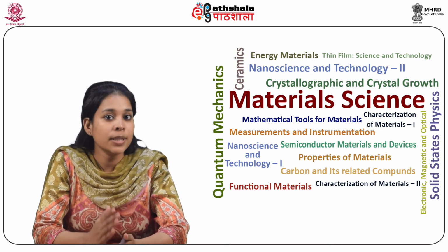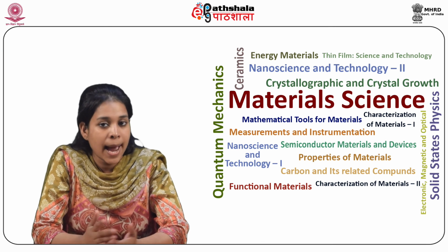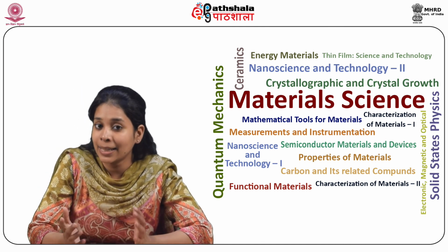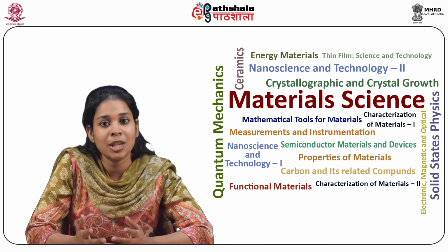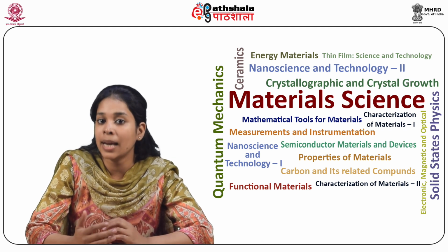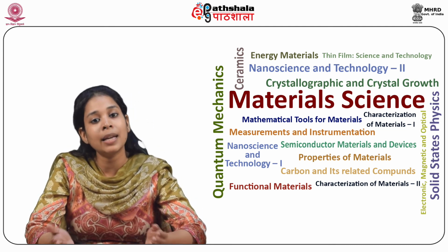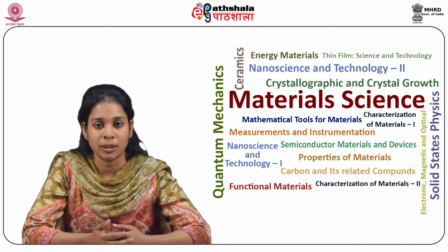So students, let us summarize what we have learned in this module. So first it was pressure assisted sintering. In this, a pressure is applied during sintering. That's why it is called pressure assisted sintering. And the external pressure directly adds to the driving force, which varies as 2 gamma by r. The concentration of vacancies near grain boundaries is increased, and there is increased diffusion of vacancies from grain boundaries to pore, leading to increased densification.